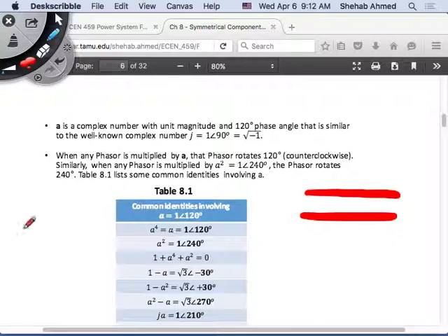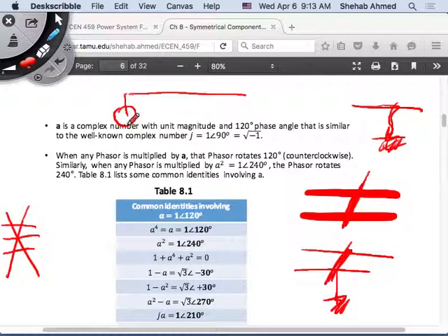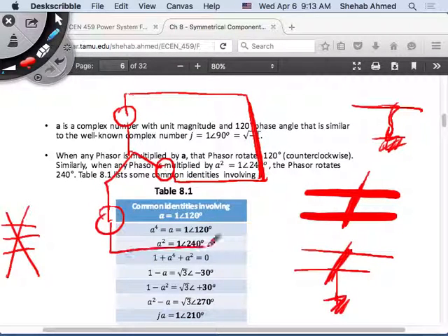We said that three-phase balanced faults, we will not discuss them. That's chapter 7. We know how to do that. Unbalanced faults are either going to be line-to-line faults, or line-to-line to ground type faults, or single-phase faults to ground. Single-phase to ground means that current is flowing from my phase to the neutral. Double line means I have my generator. This is my source, and I have these two connected, and I have this one here.